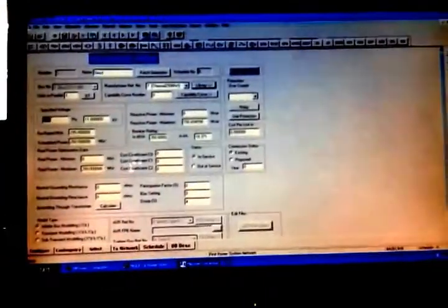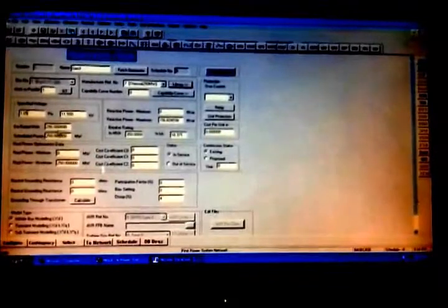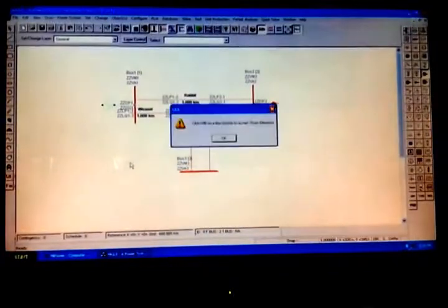Again come to specified voltage here. Specified voltage is 1.05. So derated MVA, you should enter it as 1000. Scheduled power 800. Then real power is 800. Again reactive power 600. So then save this. We have drawn the slack bus generator.